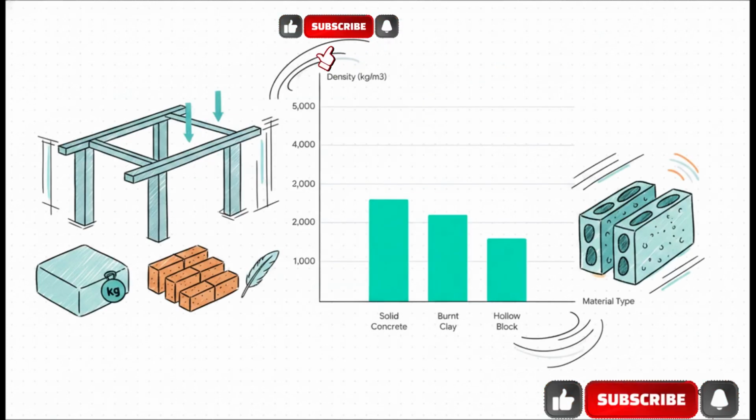The data is actually pretty striking when we talk about density. A solid concrete block sits at over 2,600 kilograms per cubic meter. Traditional burnt clay bricks are around 2,200, but hollow concrete blocks, they drop all the way down to just under 1,600. Because they are so much lighter, they drastically reduce the dead load resting on the main structural skeleton of the building, while still giving you great rigidity and fire resistance.